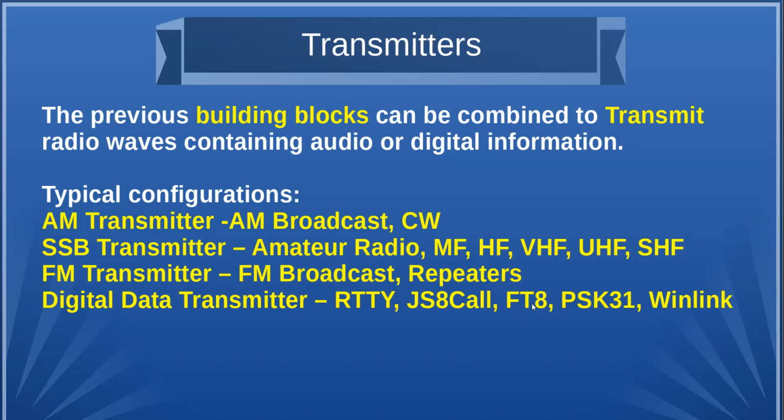Yeah. And one of the, like an FT8, the reason there's an 8, because there's also FT4. FT8 uses 8 audio tones to represent the digital word. So in essence, it can send 3 bits at a time, because 3 bits represent 8 values.